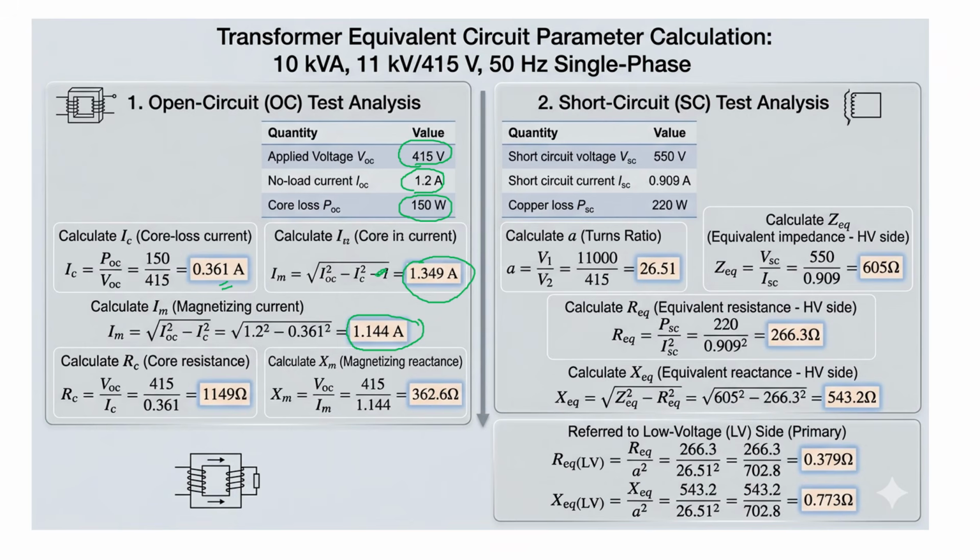So from this, we can calculate the core resistance and core reactance. This will use I open circuit, the measured total, then the core current, because it is active. So IC is obtained from this. I imaginary can be calculated by using this relation, 1.24 squared minus 1.6 squared, which is this magnitude.